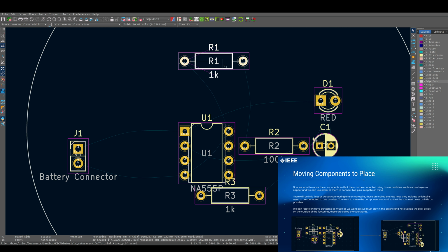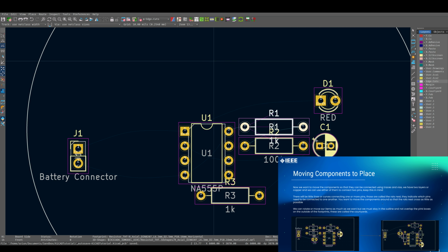They go like that. And then we can go like that, so we can go there, and then VCC connects there. This. And this is the output, so this goes right here. I'm going to press R to rotate. R once or twice. We have, let's see, VCC, VCC, VCC, dis, thresh, and then the output. That looks great.